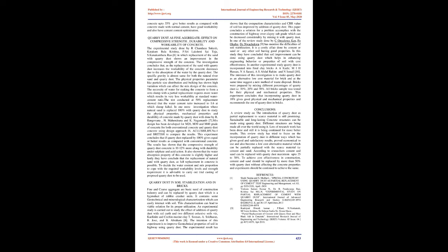Another study done by Venkata Sairam Kumar and Dr. B. Panduranga Rao, Krishna M.L.N 2 states the workability of concrete. In their experiment, they took different percentages of quarry dust with different grades of concrete, viz. M20, M30 and M40, with varying water-dust ratios like 0.5, 0.4 and 0.35 to check physical and mechanical properties of concrete. The result concludes that there is no change in workability even if the water-dust ratio is varied. Again, a decrease in compressive strength has been observed if cement is replaced by more than 25% with quarry dust.